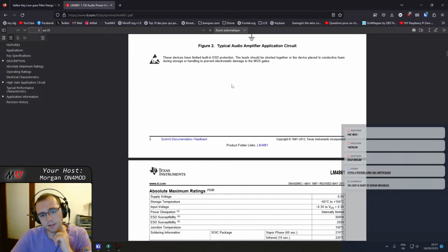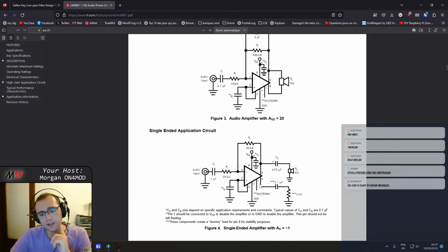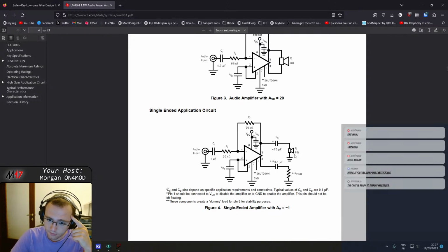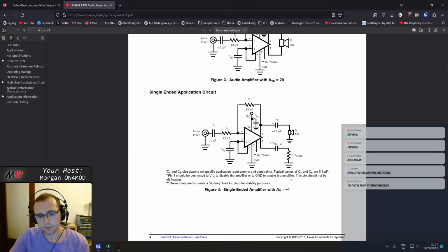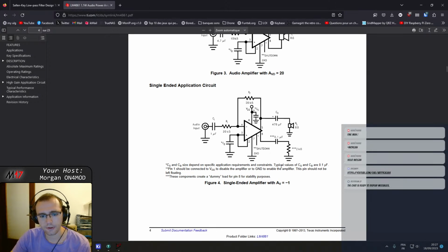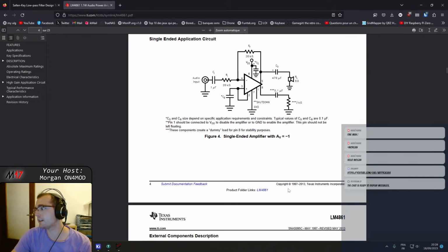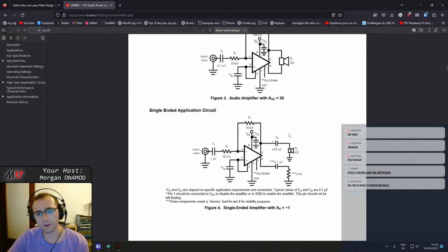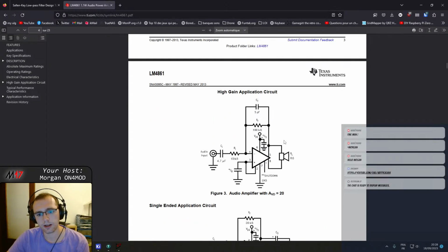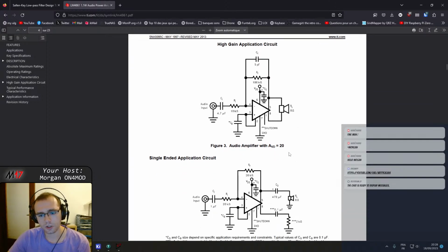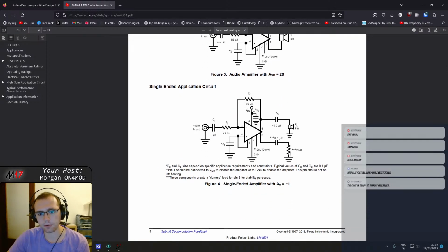So basically, we are in this configuration because we have a single-ended output for the speaker. So of course it's gonna be less than 1.5 watts because of the single-ended output. If it was a true differential output like this, then we would have twice the voltage across the speaker, which would bring 4 times the power.